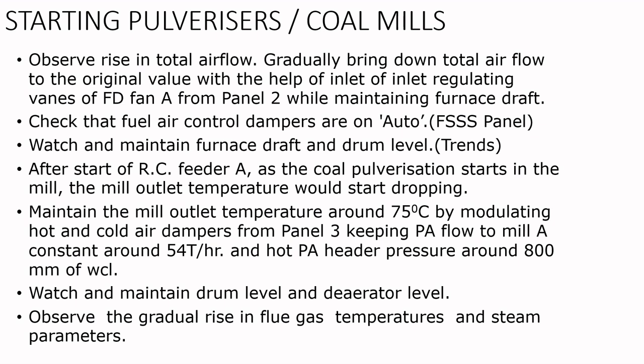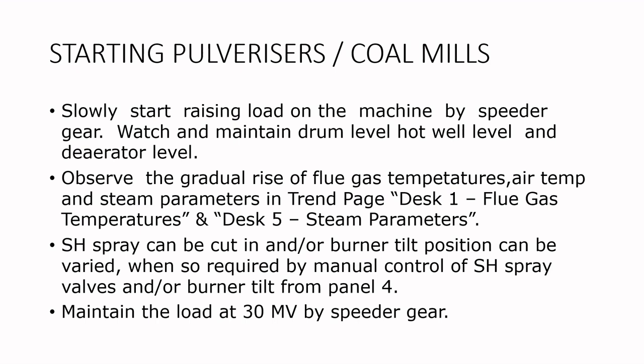Now slowly start raising the load on the machine by the speeder gear. So you should operate the speeder gear at this point. Now watch and maintain the drum level when you operate the speeder gear, the hot well level and the deaerator level also. All these three levels you can watch. Now observe the gradual rise in flue gas temperatures, air temperatures and steam parameters in trend page desk 1 flue gas temperatures and desk 5 steam parameters.